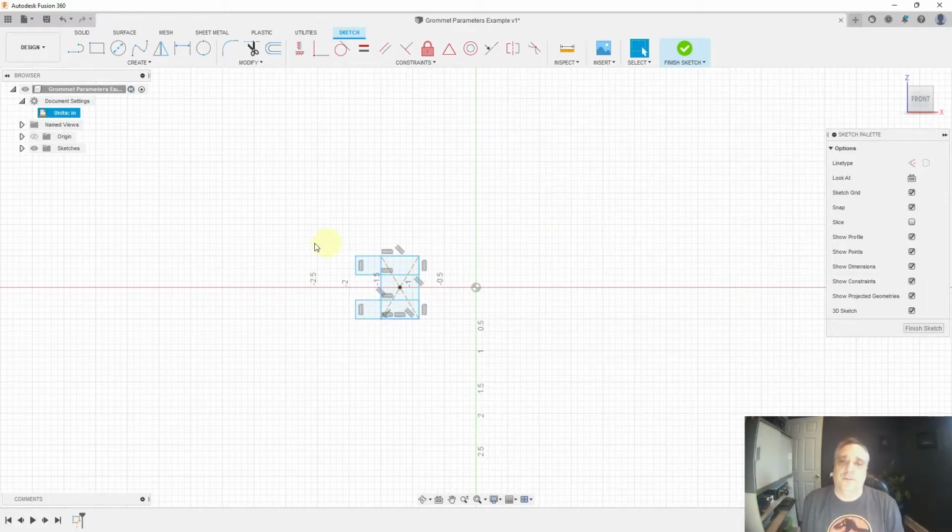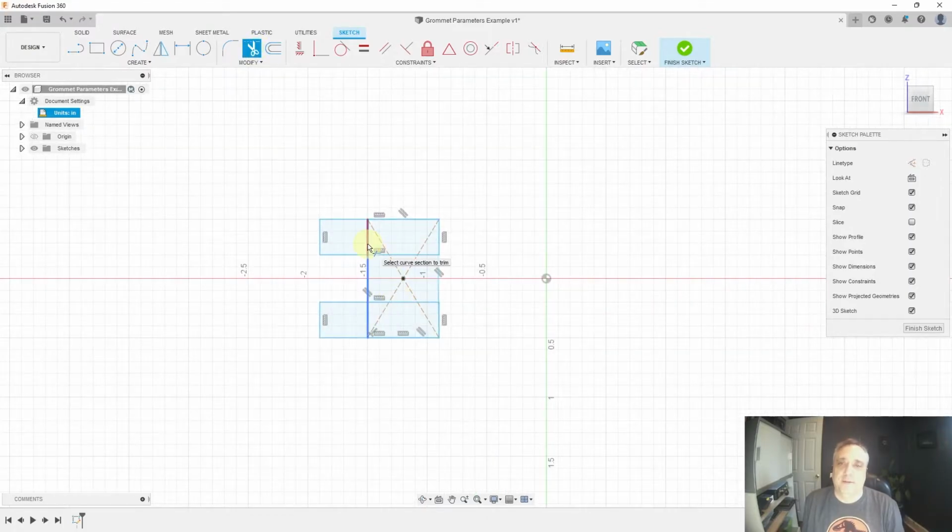Now I'm going to start cleaning this up, and if you hover on this, you can see there's a lot of overlapped sections, and I'm really just going to start trimming away some of the fat. So don't need that, don't need that, don't need that. There's a couple of them there. Don't really need these lines for now, because we're going to just reconstrain this whole thing.